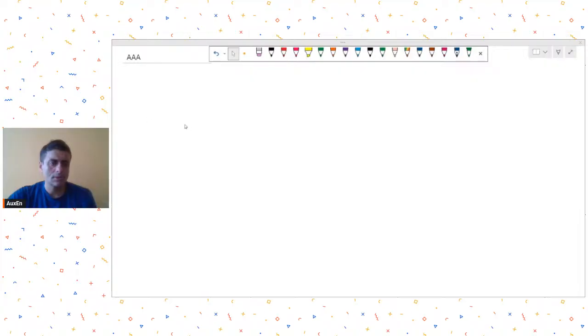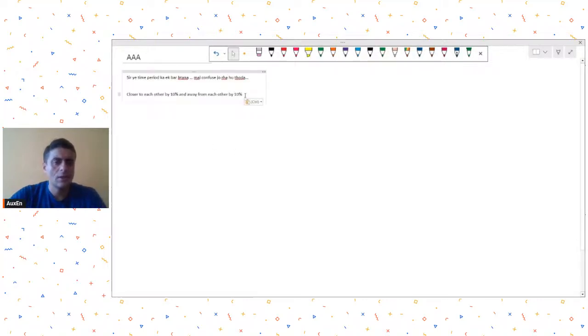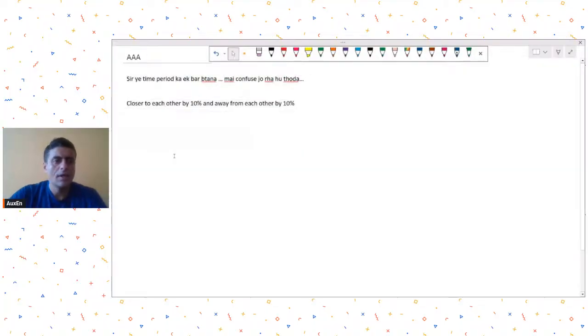So what he is asking, he has this doubt regarding the clause that is given in IS 1893 about that time period lateral irregularity, where the time period needs to be 10% away from each other. So regarding this clause, he has certain queries.